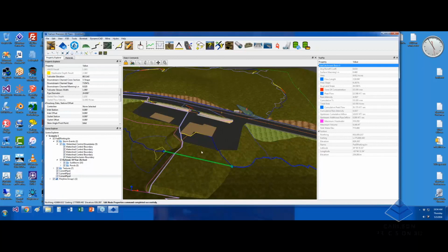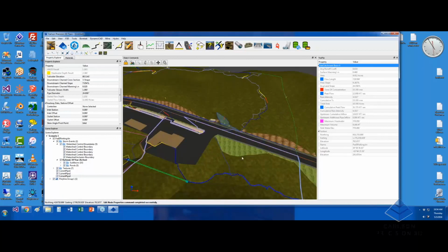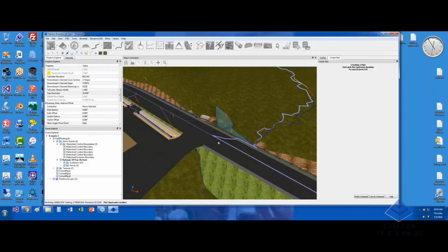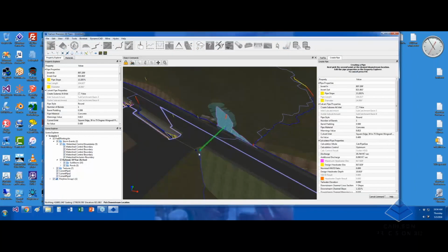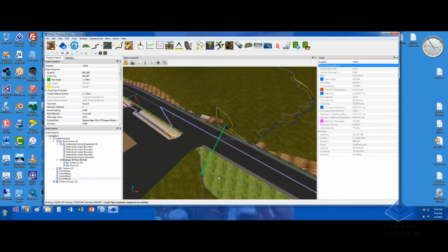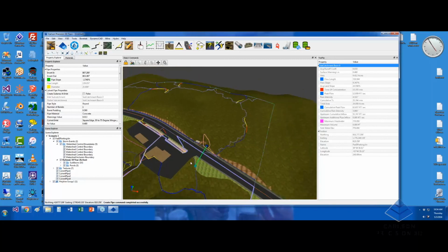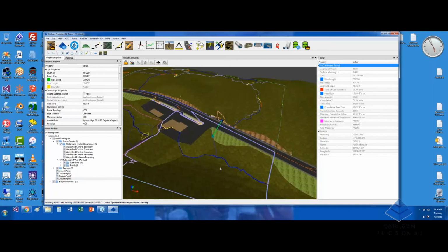And the other thing I can do is quickly drop in another culvert from across the road. Make sure that the pipe slope goes green, which is negative. So as I'm drawing it, I can see where it drops to green, and I'll just select that. And we get an automated headwater calculation, and we get a 21-inch pipe in that particular. And now if we look at the sub area, we're up to 62 cubic feet per second coming into here from all of these different areas.